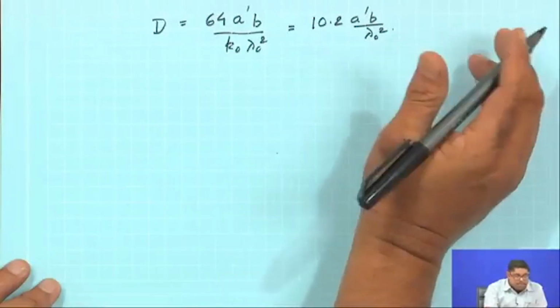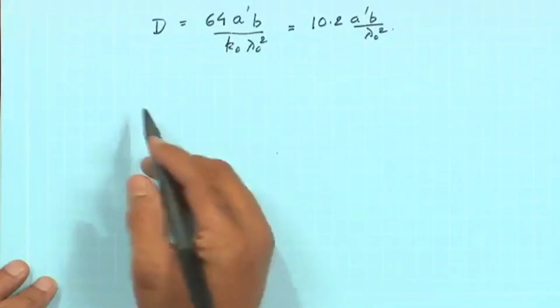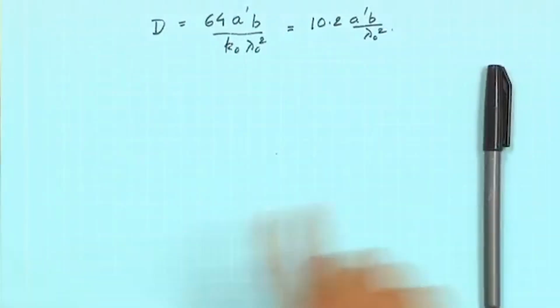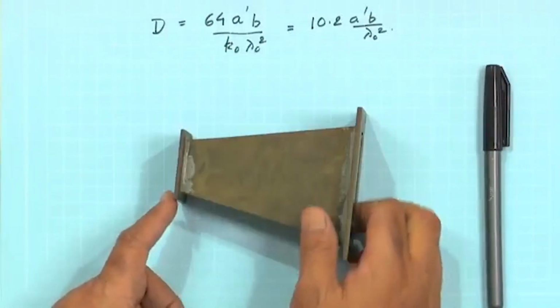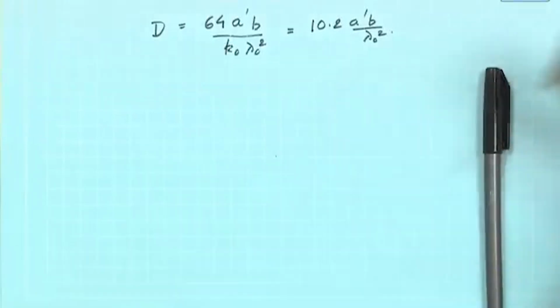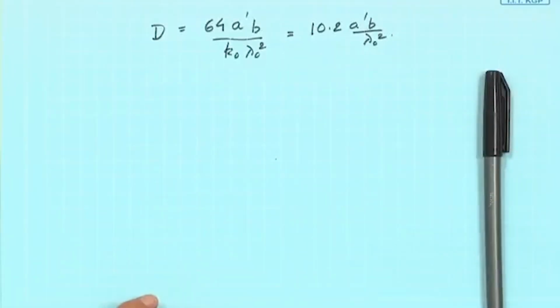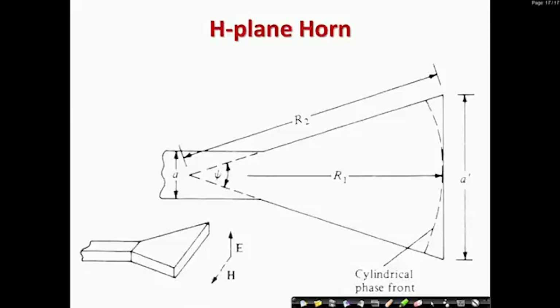You remember that at microwave frequencies the gain of a horn is essentially equal to the directivity, as losses are negligible. Now, if the horn length is fixed, but I want a higher gain, then it can be obtained by increasing the flare angle to some extent, which will cross that pi by 4 restriction on the phase error.